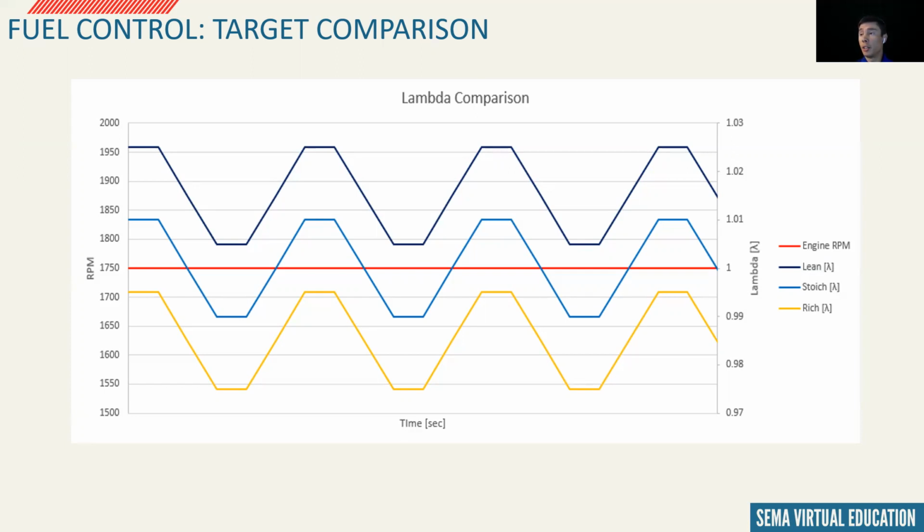This will help the conversion of all species using our three-way catalysts: lean to oxidize hydrocarbon and CO, and rich to reduce NOx. The peak-to-peak transitions will last about 800 milliseconds at lighter loads and lower engine speeds, like we have represented here, and 300 to 400 milliseconds at higher engine speeds and higher loads.